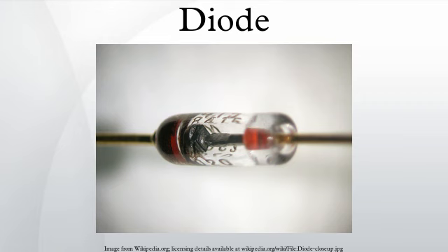In certain real-world cases, it can be important to consider the losses incurred by this non-ideal diode effect. However, when the slew rate of the current is not so severe, the effect can be safely ignored. For most applications, the effect is also negligible for Schottky diodes. The reverse current ceases abruptly when the stored charge is depleted. This abrupt stop is exploited in step recovery diodes for generation of extremely short pulses.